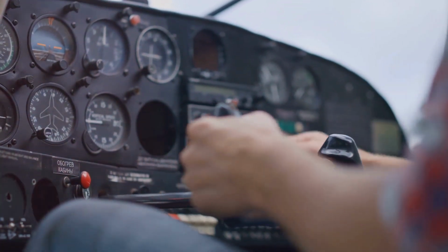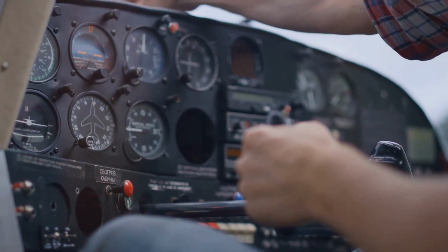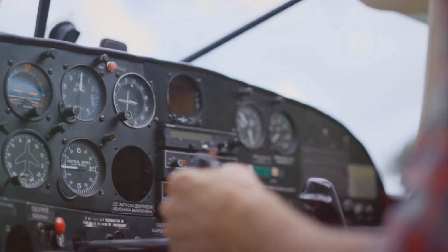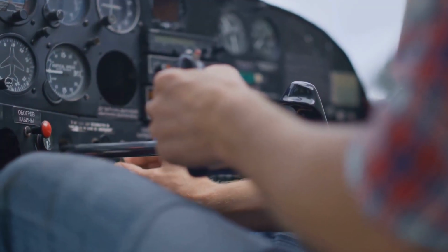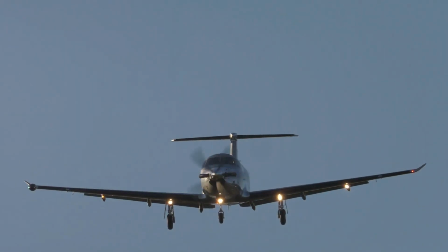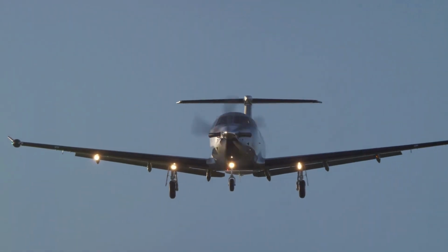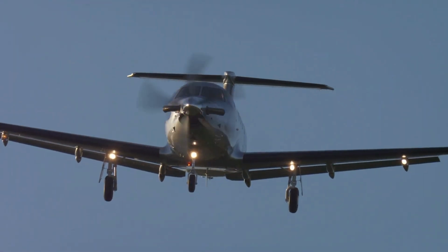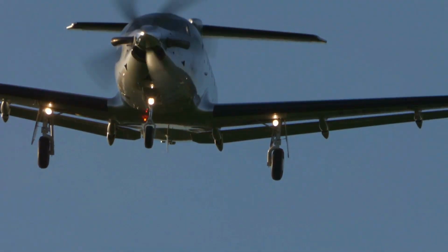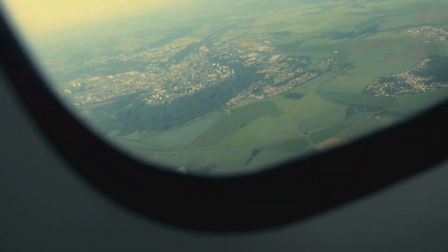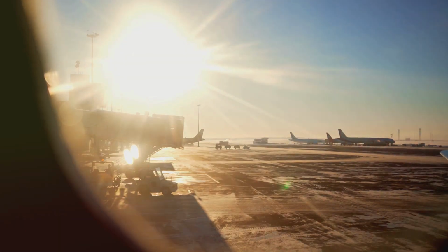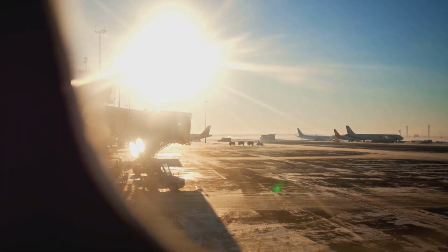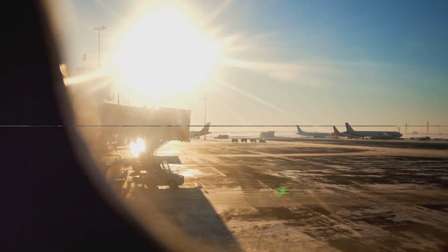Firstly, we have the indicated airspeed or IAS, which is the speed shown on the airplane speedometer. Then there's the calibrated airspeed, CAS for short, which is the IAS corrected for instrument errors. The equivalent airspeed or EAS considers the effect of air compressibility for planes that fly over 500 kilometers per hour. The true airspeed TAS is the EAS corrected for changes in air density. Lastly, we have the ground speed GS, which is the airplane's speed relative to the ground. In the coming scenes, we'll delve deeper into these speed measurements and understand their importance in aviation.